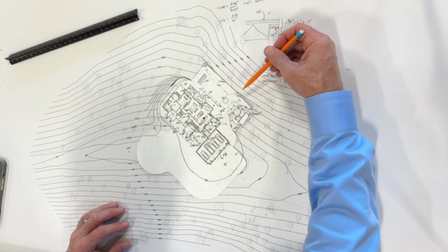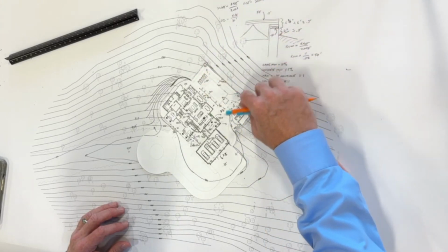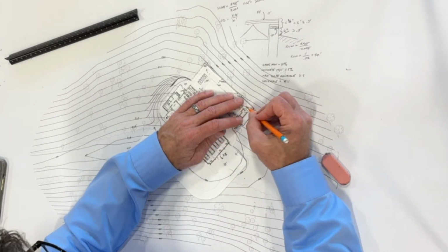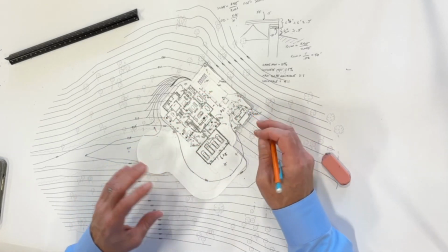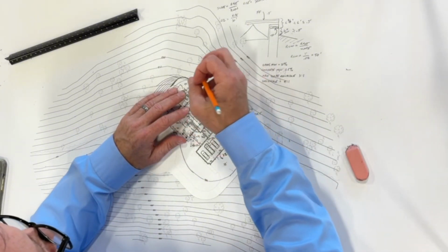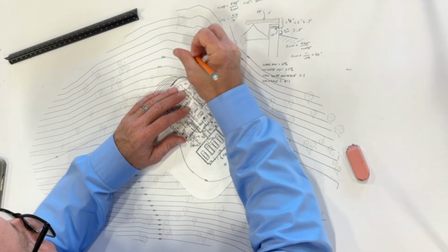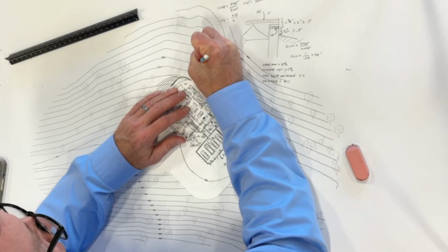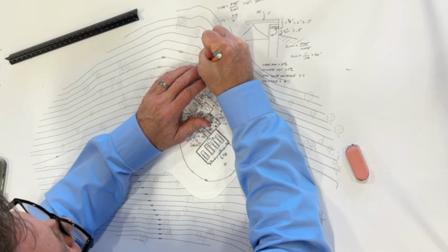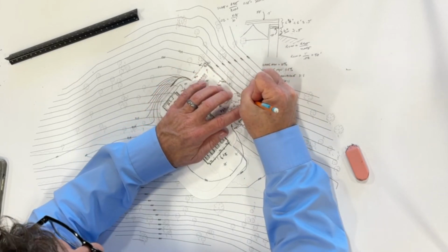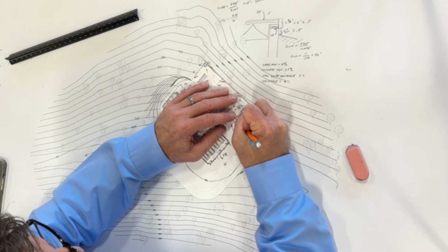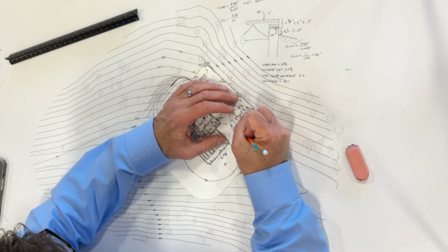Because we have a retaining wall back here, we don't have to touch any of these trees or grade or anything. So now over here this 940 goes to the edge of the retaining wall, but then it's going to drop on the retaining wall down to what's below it. So now we look at how high is this retaining wall. Well, this is a 940 wall. This is 9 foot back here, 10 foot, and that's a 929. So that's 11 foot. So it's an 11 foot high wall across the back. Becomes a 10 foot high wall here, 9 foot, 8 foot, 7 foot, 6 foot.